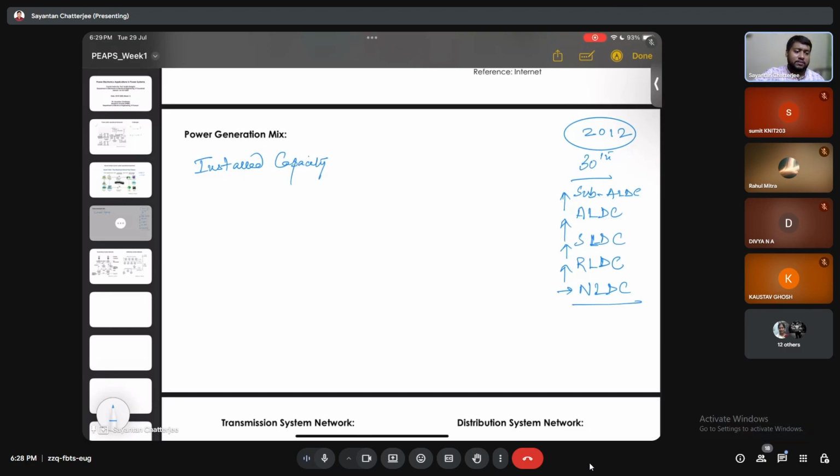In this way it was a cascading failure. The catastrophe happened in the western grid; the northern grid couldn't isolate, but the eastern and northeastern grid isolated. On the next day, the 31st, after all the work was done, when people tried to synchronize all these 4 grids, all 4 grids went out.